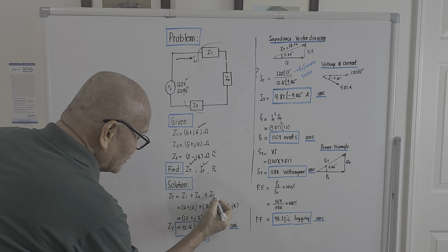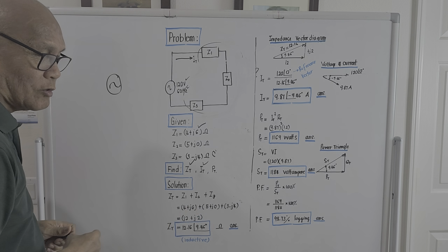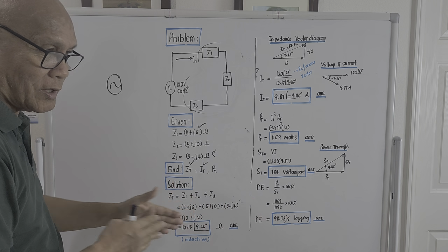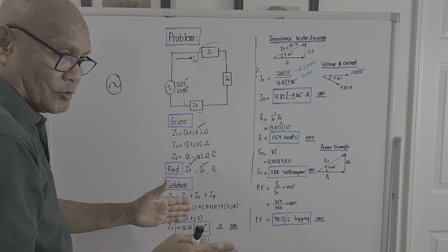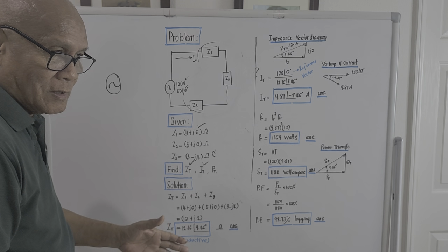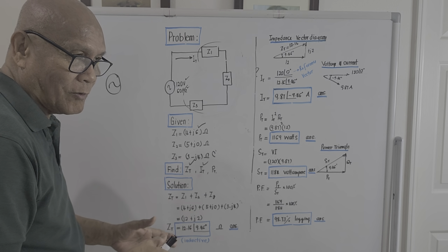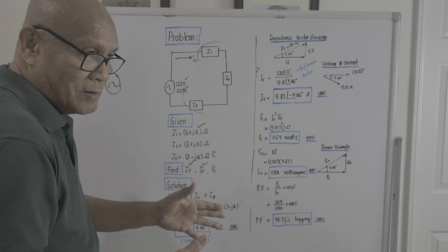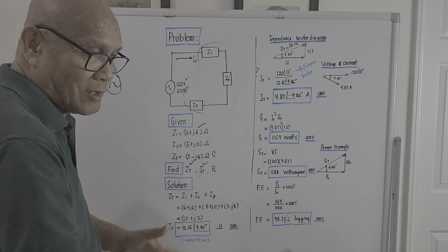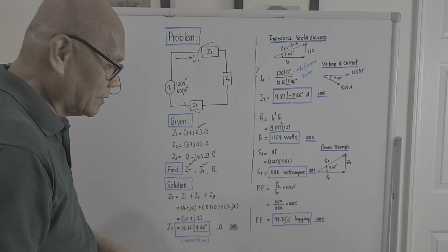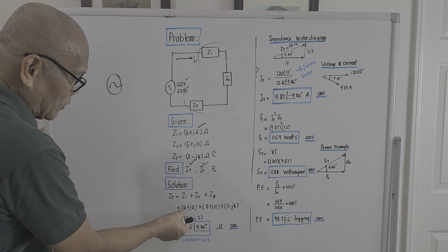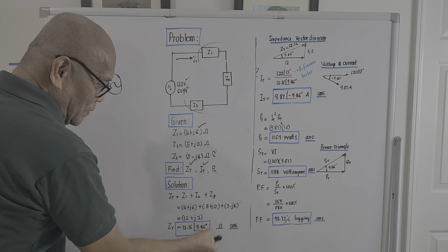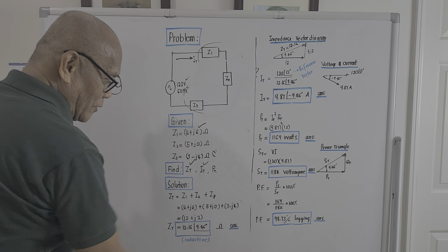the individual impedances are actually expressed in the so-called rectangular form, so there's no more problem on how to convert from polar to rectangular. They are all rectangular already. So if you are taking the board exams, and the given impedances are all in rectangular form, there will be a time that you will be adding. Because they are in rectangular form already, we are ready to add. So substituting values: 4 plus j6 plus the quantity 5 plus j0 plus the quantity 3 minus j4.